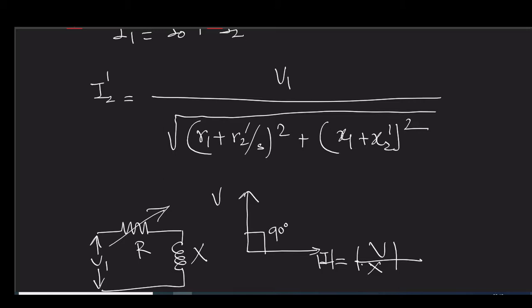And this is for r equal to 0, and when r is equal to infinite, the current value will become vanishingly small, but at that time this circuit will start behaving like a resistive circuit. So the current will be in phase with the voltage. So I have explained it in detail. You can see that your current locus will form a semicircle